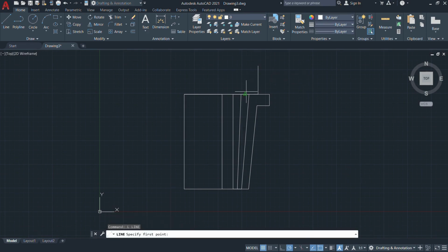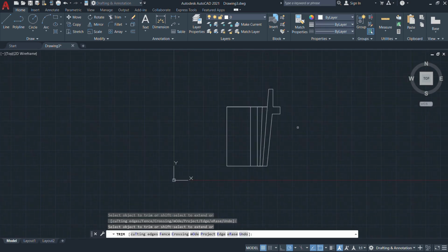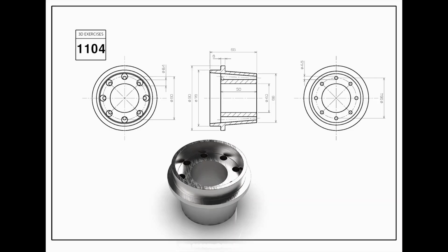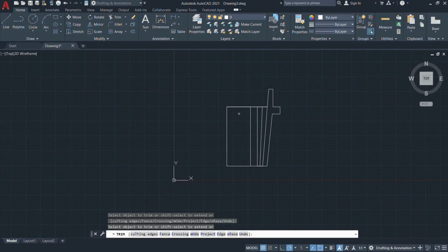Okay. Then choose a line again. Start from this particular point. Based on the reference, we can easily draw in collinear directions from the reference entities and close the entire profiles. Again type the command tr in the command line. Then trim the rest of the portions which we want to remove. The sections are totally removed, and the right portion is covered.